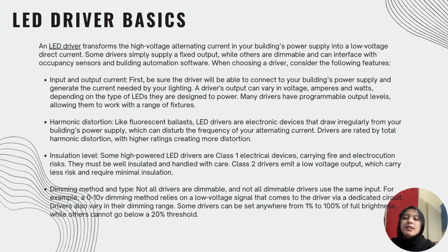Insulation level. Some high-power LED drivers are Class 1 electrical devices, carrying fire and electrocution risks. They must be well insulated and handled with care. Class 2 drivers emit a low voltage output which carry less risk and require minimal insulation.